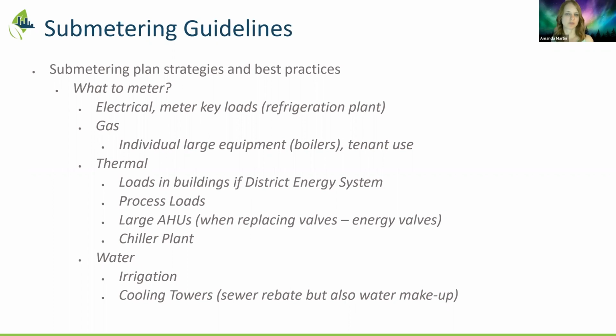And then, as I alluded to earlier, we've also added sub-metering systems on larger energy saving retrofit projects so we could complete M&V. Typically, if the load isn't dispersed across the building, but we're targeting a specific asset, then we can add a meter to it. If it's something like a recommissioning, where it touched everything across the building, then we would use the interval meters.